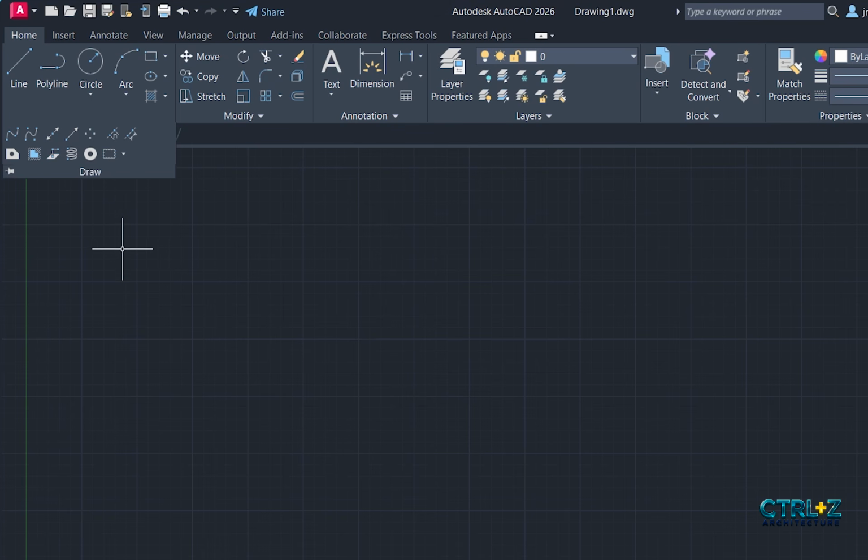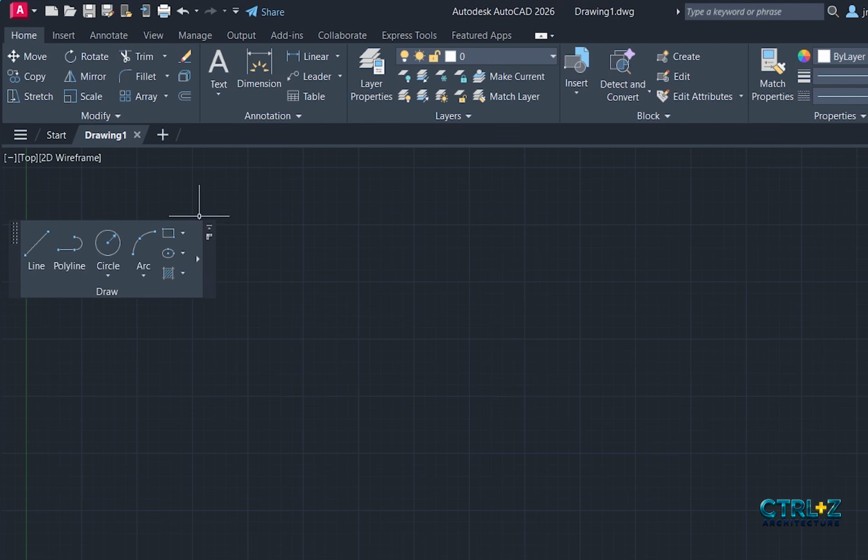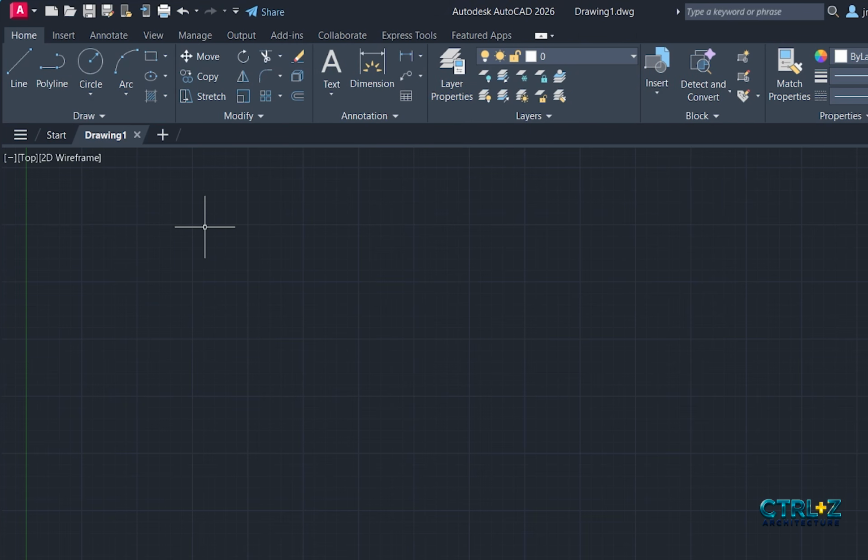These panels can be moved around out of this ribbon area. Now if you move this panel out, just simply drag the bottom corner of the panel. And now, this will work like a floating panel, and this remaining tab will slightly adjust. If you want to move it back to its original location, you can drag it back or simply hover your cursor to the panel until some invisible icons show up on the right side and click on the Return panel to the ribbon. It will automatically return back to the Home tab.